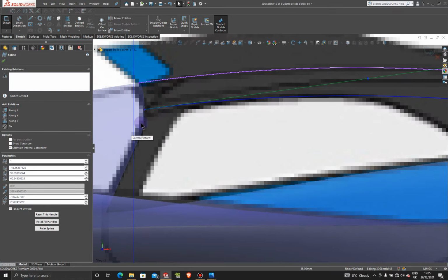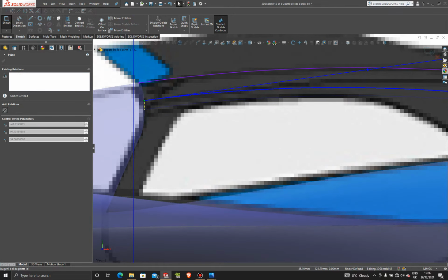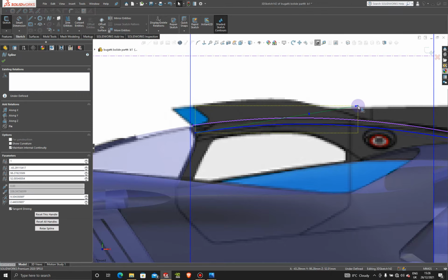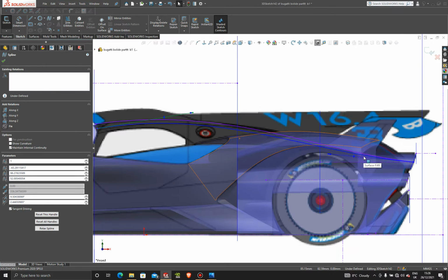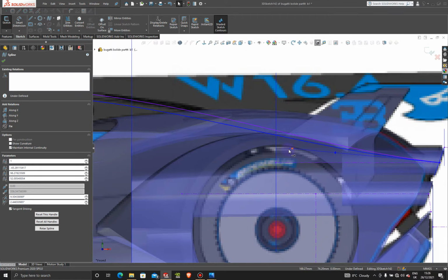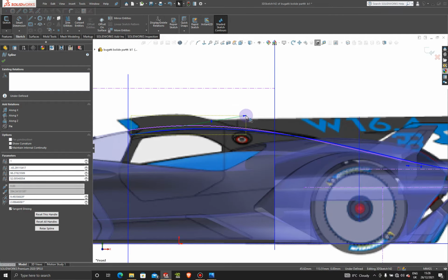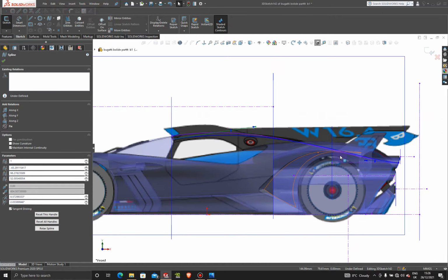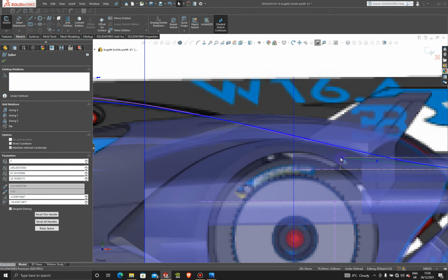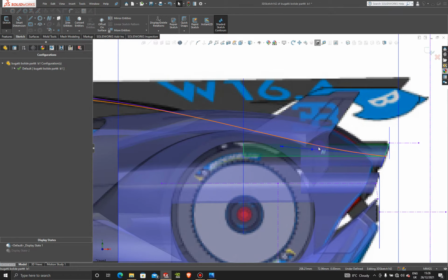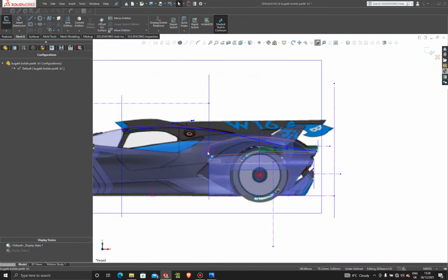Okay, so we can see already that we need to pull this line up to accommodate the window pillar, and we will check the tolerances, what the blueprint will let us do. So we're going to pull this up to here, and following that line. And of course, with this sketch, we also want to make sure that we are following our first sketch here. So let's pull that line to about here to accommodate that line, and then pull this line to about here, and then let's just click on this line and make sure that we will have a nice bleed onto that surface, and it looks to be all right from this side.